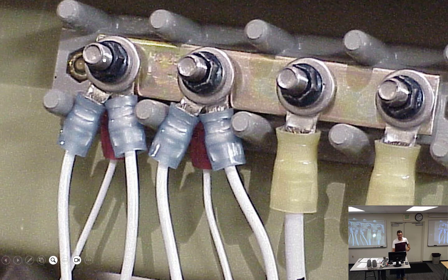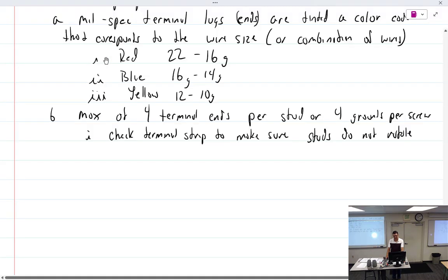These studs should not rotate. They're actually usually bolts that go the other way. If we did see where somebody took a huge bundle of wires and slapped it onto one stud, would we try to spread it out across them? I would. Or drill a new one? Drill a new one. Find a different spot. Put it somewhere else. We get the ground loop thing, right? Yeah. Okay.